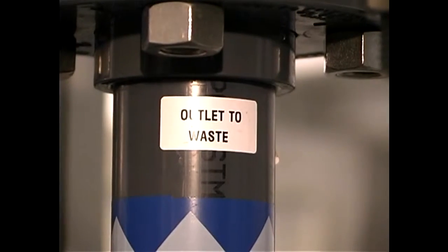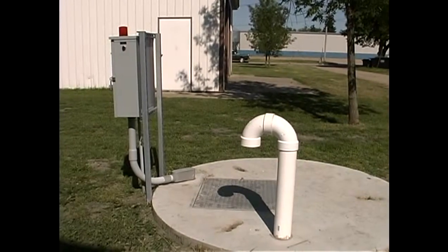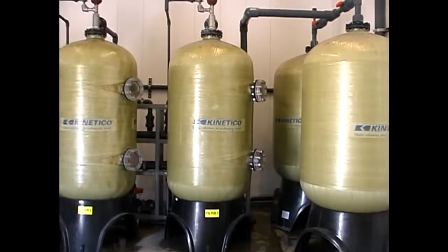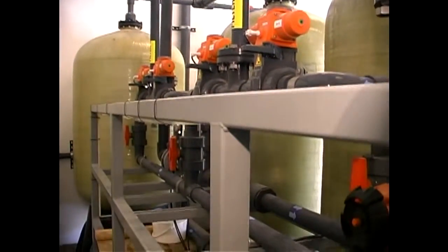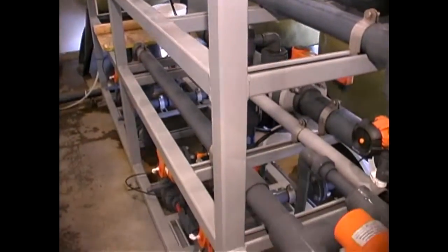You know, chances are when we're making backwashes, we lose a little bit of media. And all we have to do is just add media to it. The backwash water is discharged to the sanitary sewer via a newly constructed lift station. The plant produces a finished water arsenic concentration of 5 micrograms per liter or less, an adequate margin below the new MCL of 10 micrograms per liter.